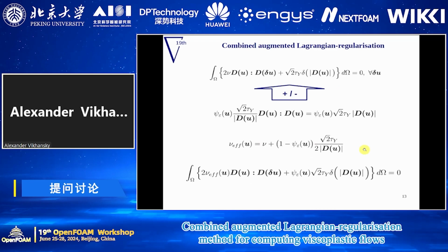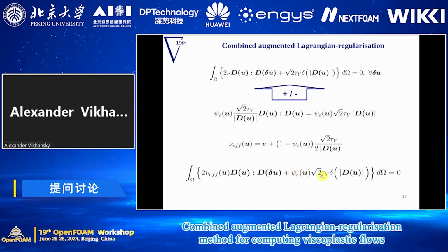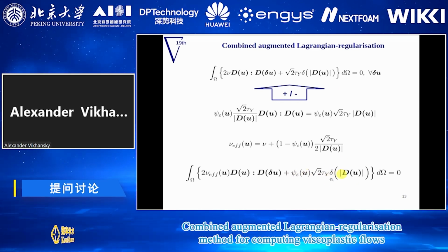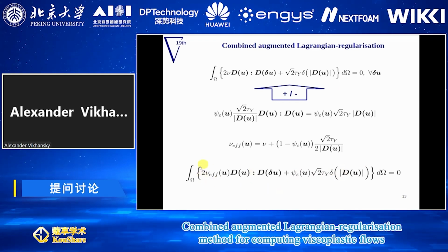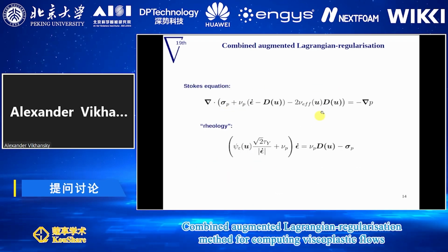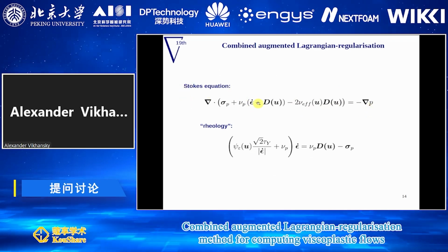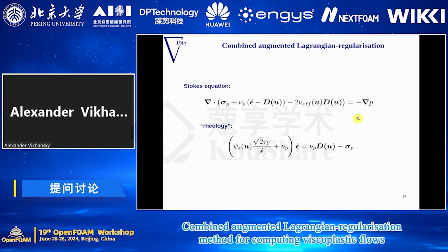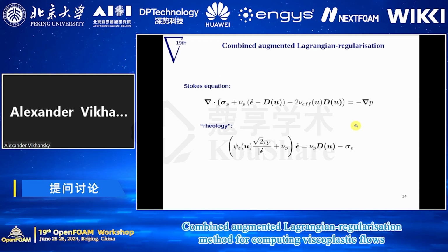Now, if you introduce a regularization, you basically transfer a significant part of the plastic stress from this part to the usual viscous term, right? So it means that now it is directly inside the Stokes equation, and it helps a lot in stabilizing the calculations.